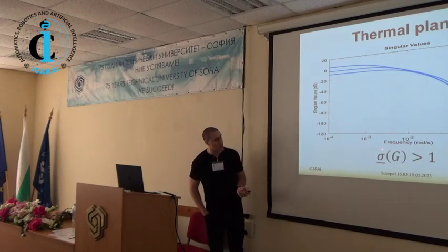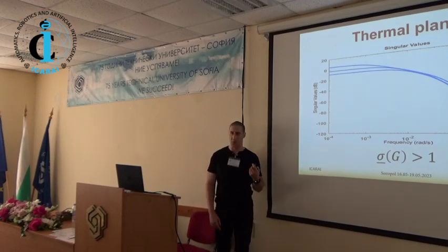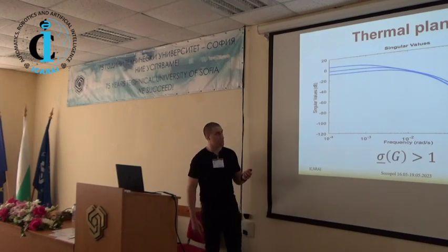For perfect control, we would like the smallest singular value of the scaled plant to be over 1. Above the equation, I am showing you a graph of the singular values of the scaled plant, which shows that for sufficiently large reference change or disturbance change, we will hit the saturation limit. So this will be a problem, and I will show it later.